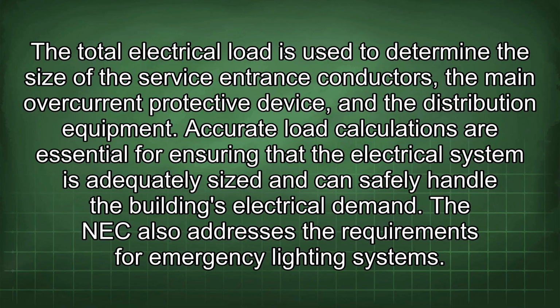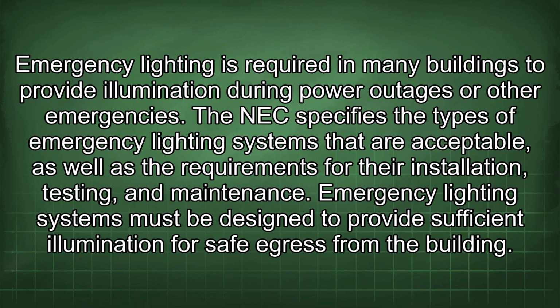The NEC also addresses the requirements for emergency lighting systems. Emergency lighting is required in many buildings to provide illumination during power outages or other emergencies. The NEC specifies the types of emergency lighting systems that are acceptable, as well as the requirements for their installation, testing, and maintenance. Emergency lighting systems must be designed to provide sufficient illumination for safe egress from the building.